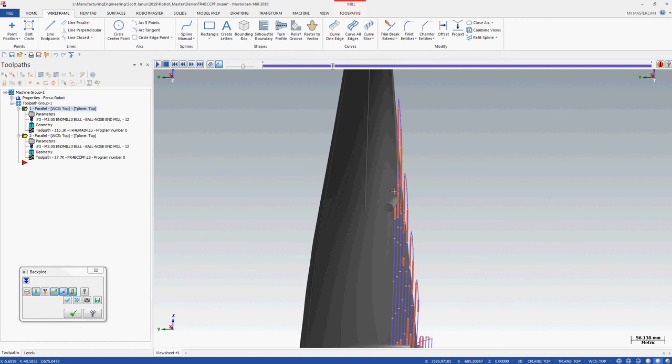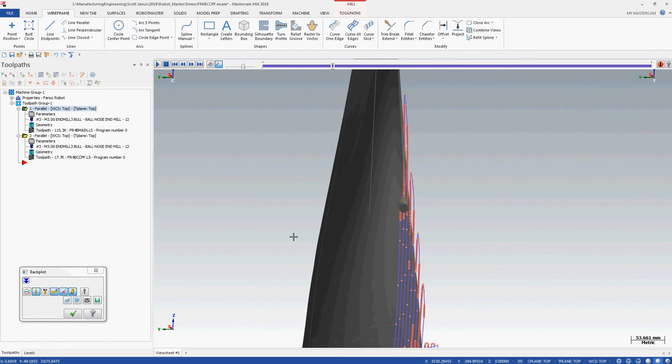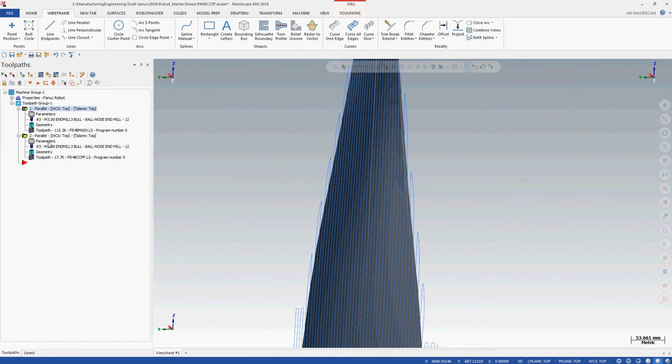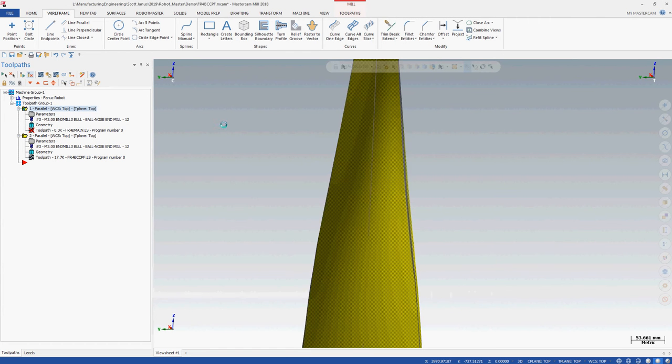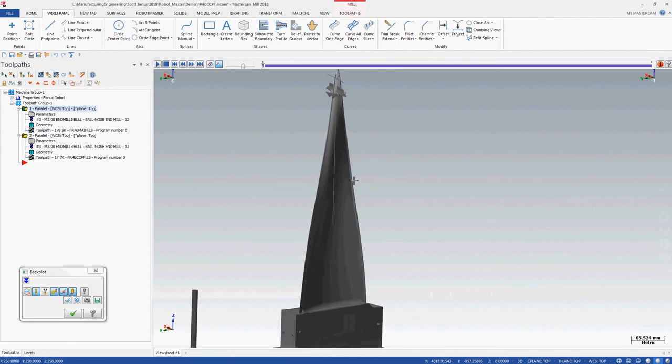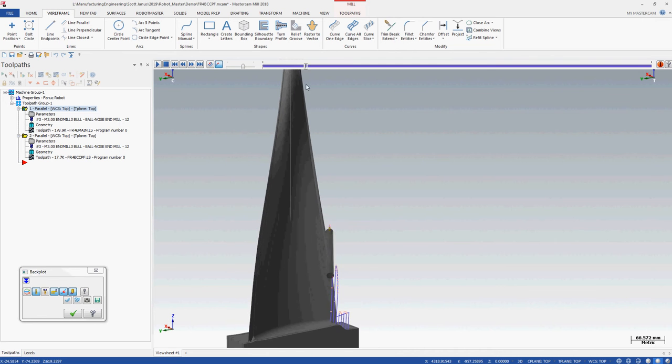And if I go into cut pattern, this is how I'm maintaining my tool axes in X and Y. And I have some advanced features, so extend and trim. What this allows me to do is if I want to extend my tool path up this way, I just change my tangential extensions to 25 millimeters, so it goes up.